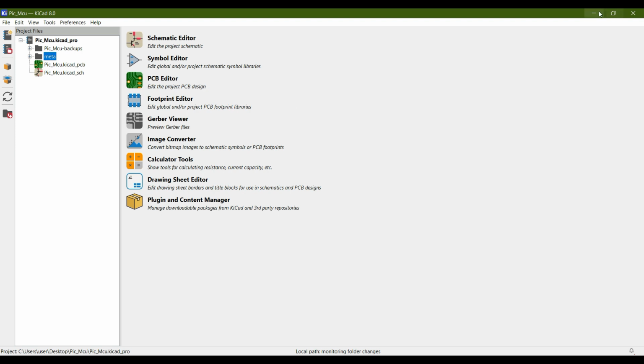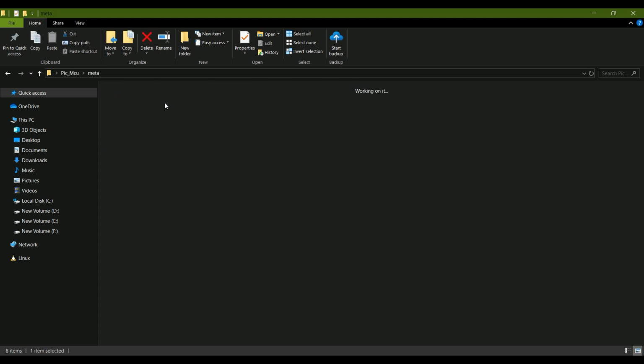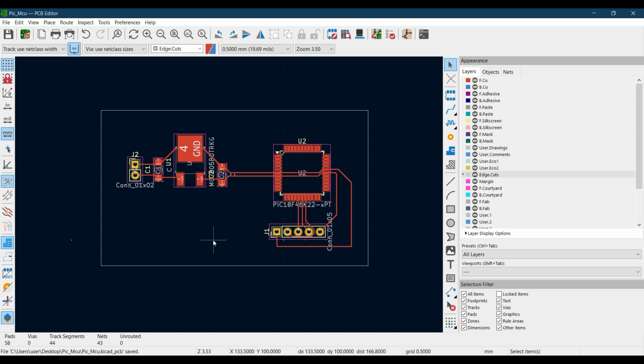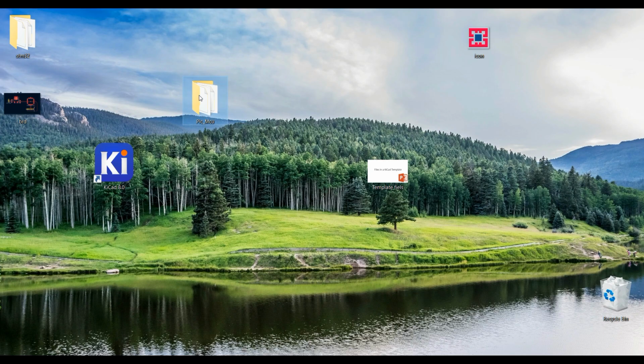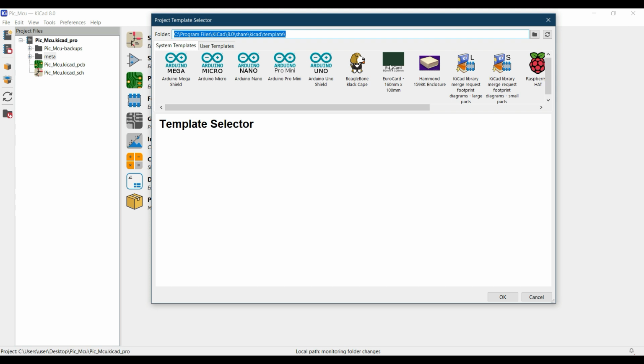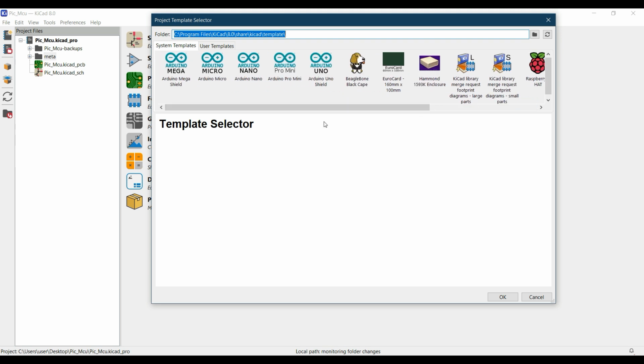The next step is that we want to add a description in the info.html over here. Let's open this. I think it's better to do this in the next video. So till now we have designed the schematic and the PCB of the template. In the next video we will see how we can place or use this folder in the templates of our KiCad. As you can see, if you go to File, New Project from Template, you don't find the template we have currently designed, because we haven't yet placed this template in the template directory. So see you in the next video.